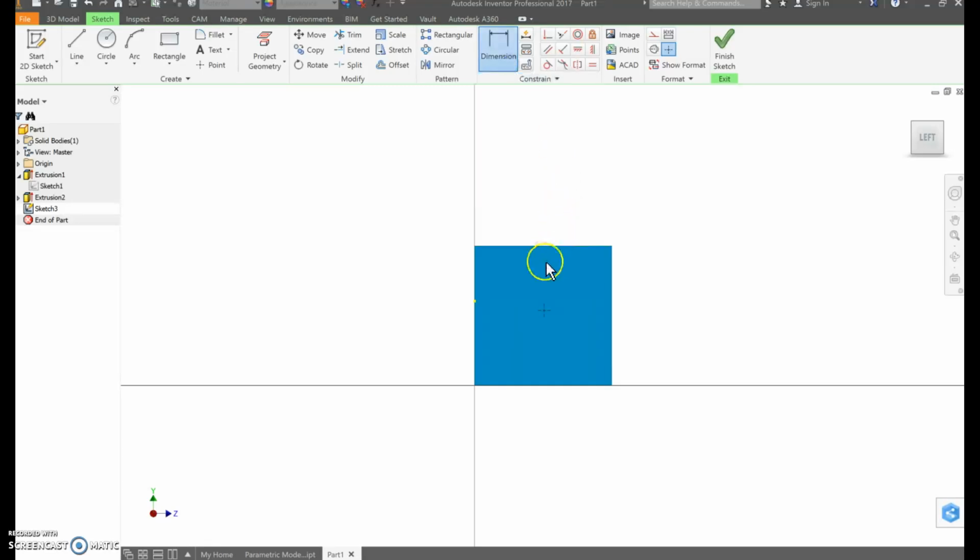I'm going to start by clicking on the point. I'm going to go up to the top and click on the top line. And notice it didn't work. This sometimes happens, so I'm going to hit escape, hit the dimension tool again, and try that one more time, going from the point to the top line. There it worked just fine, so I'm going to click and type in 0.5 inches. Now it's centered vertically, or up and down.